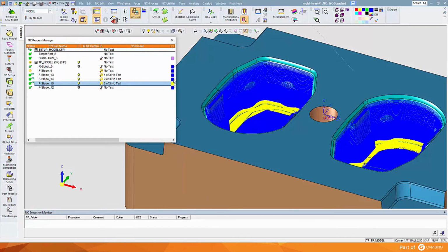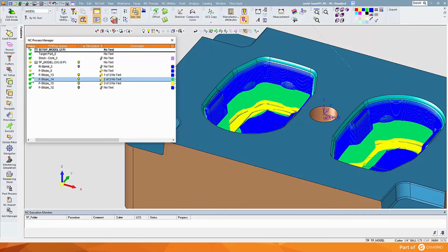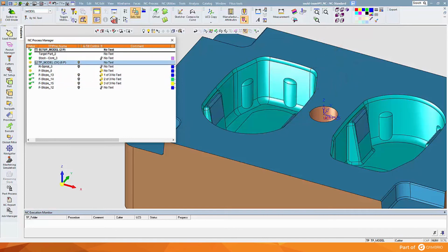By separating the procedure by tool change, we're able to see the true result. The shortest cutter not only machined the highest detail, but it also machined a large part of the floor detail. Only longer tools were used where the shorter could not reach.